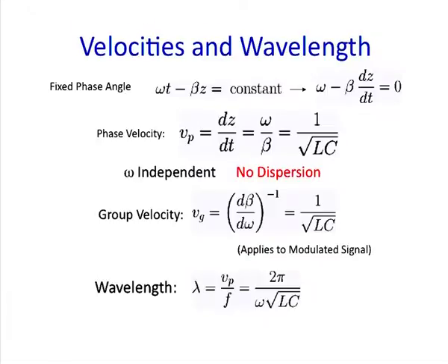The points on the transmission line over which the total phase shift takes place by 2 pi, or a full cycle, we define as the wavelength lambda, that is 2 pi by omega under root L C.